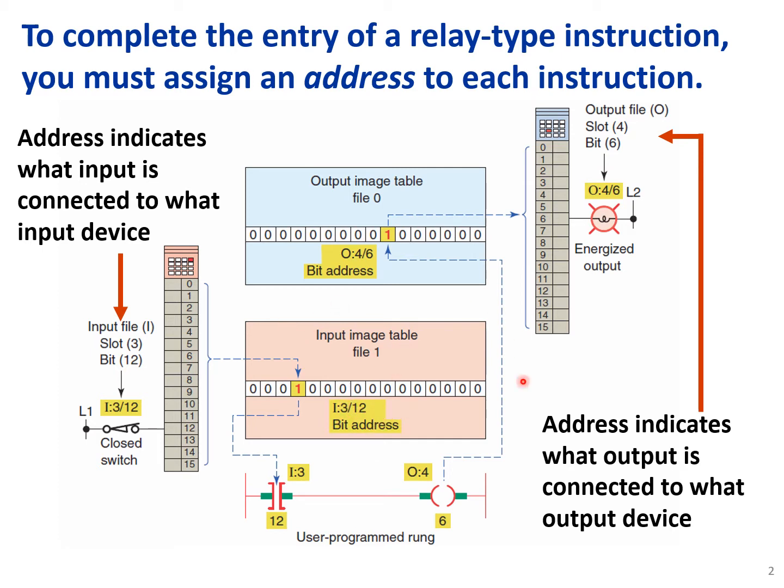So this is the image table that shows where the address is. The contact evaluates this memory bit in every cycle and sees if we have any updates. At this moment, it checks the memory bit is 1, which is true. So the logic here holds, and the output will be updated and will be true now.